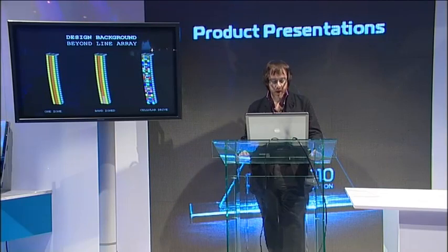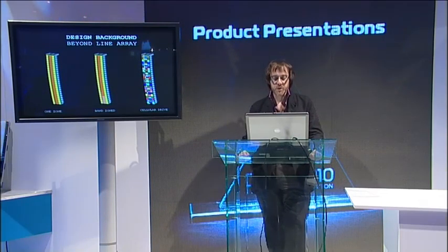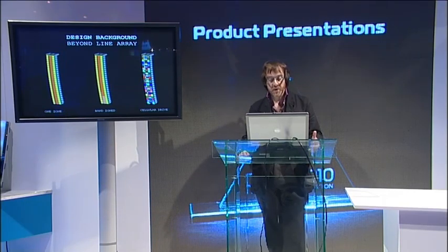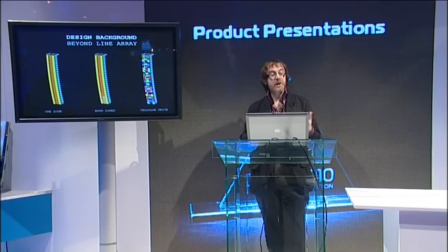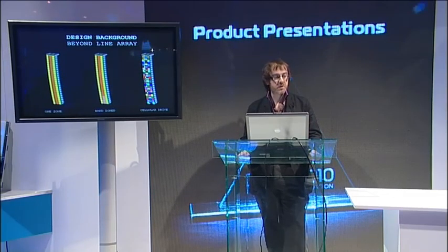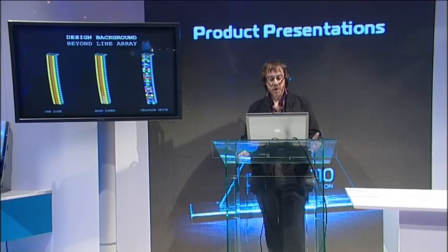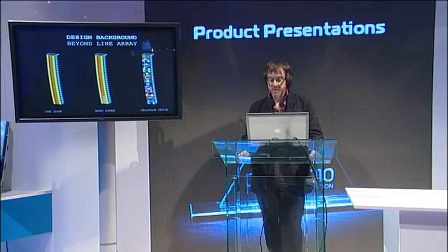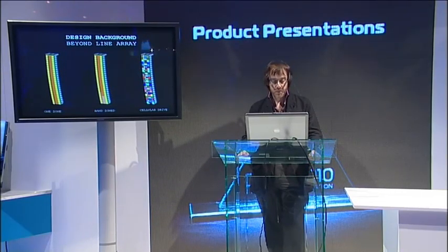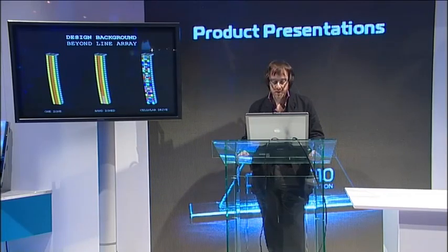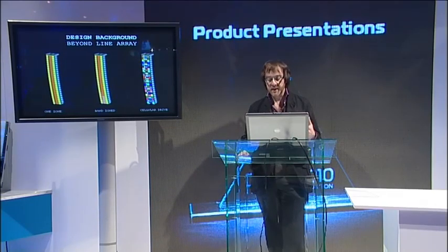So, the design background. Early touring line arrays were usually driven by the same audio signal throughout, i.e. one-zone systems like you see on the left. And today, touring line arrays tend to be driven in 3 or 4 zones to which different EQ can be applied in order to linearize, regularize the output of the system throughout the venue. But simple zoning like this is too coarse to reproduce the engineer's desired balance and level throughout a large venue. In contrast, a 24-box MLA array has 144 individual cells, each automatically EQ and level optimized for the audience profile.